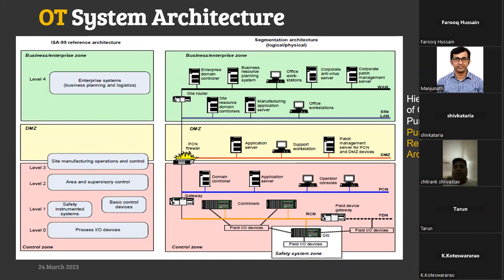And also definitely you understand the communication protocol between your controllers and HMIs, and most of the time there will be third party systems communicating to the main DCS systems or PLC systems, SCADA systems. So understanding the communication protocol is also very important when you are moving to OT security, right?